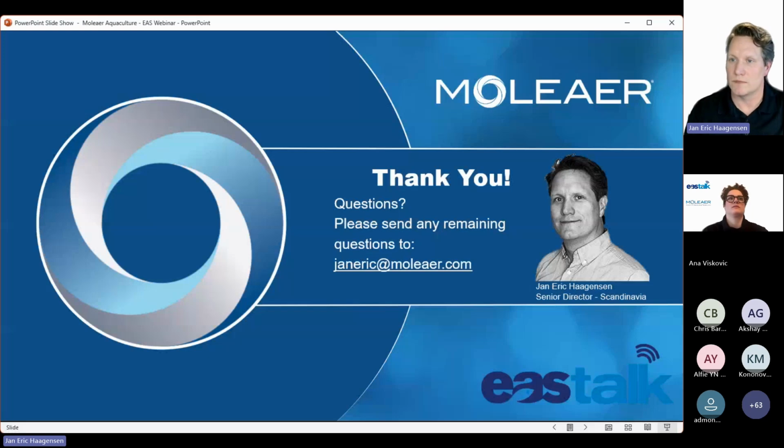Completely honestly, cones can have a fantastic transfer efficiency in itself. We are speaking about injecting oxygen into water at higher pressure, and you're able to have high oxygen percentages in that water. Cones in themselves don't produce nanobubbles, so there's one obvious thing. I'm not going to stand here and say that we necessarily oxygenate much more efficiently when it comes to the injection than a cone, but the utilization of the oxygen with immediate injection and movement of that water can be more efficient than the usage of a cone, and the concentration is more aligned with the need.